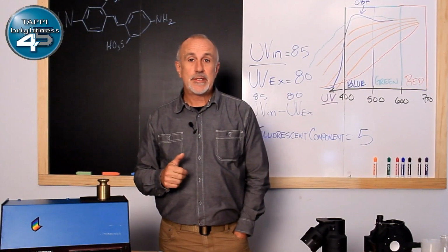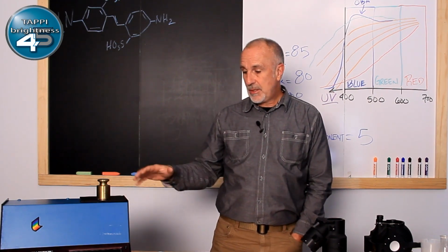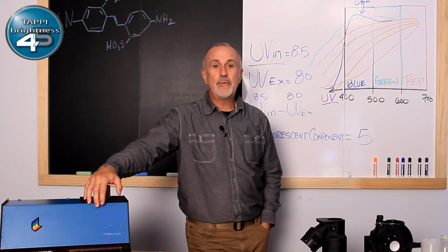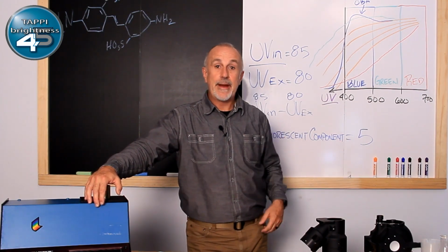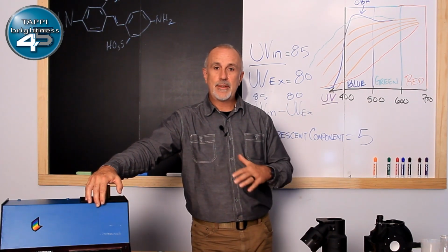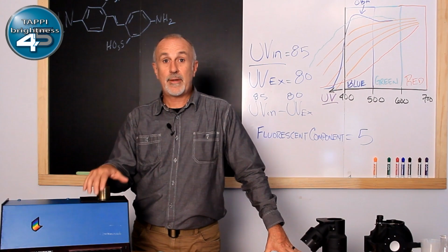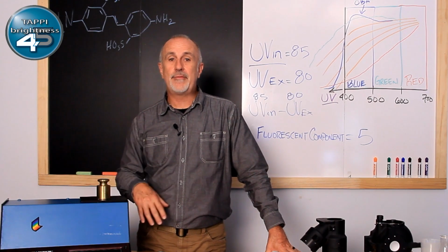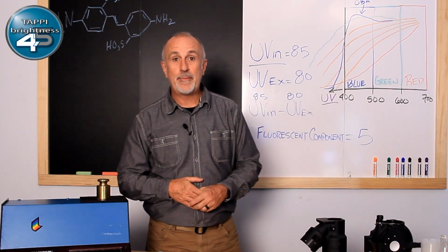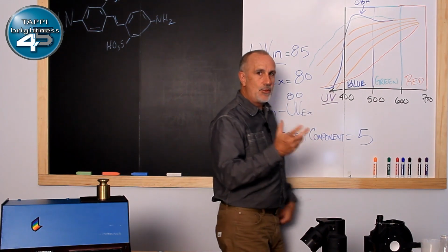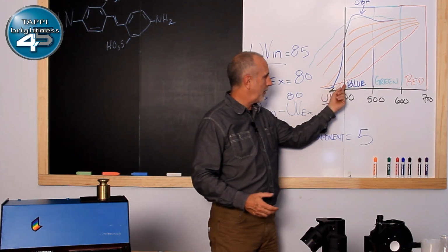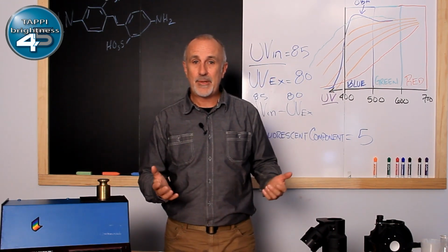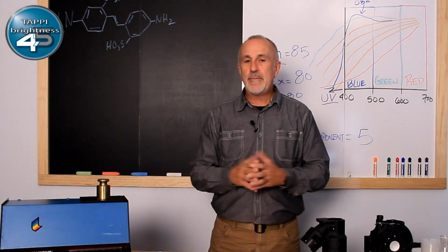So back in the 1930s, as they were doing the analysis and setting all this up using that tungsten lamp, that was what we were doing. And then all of a sudden we start throwing these optical brighteners in there, and now we're having to measure that with this. And so the TAPPI methods group went back and said, okay, we need to look at this a little bit closer to make sure what we've got set up here is the best technology for monitoring the addition of optical brighteners. And so they looked at the UV source that we had, and like we defined earlier, it's a relatively small amount of UV energy, but again, not too different from the typical indoor viewing environment, so it seemed like it would be a good match.